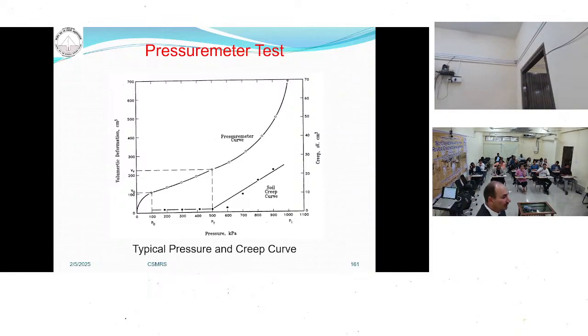So once you have determined the pressure and the volume of water that has gone to inflate your probe, you calculate the results. This is the curve from when you started inflating it. Up to here, there is no increase in pressure.